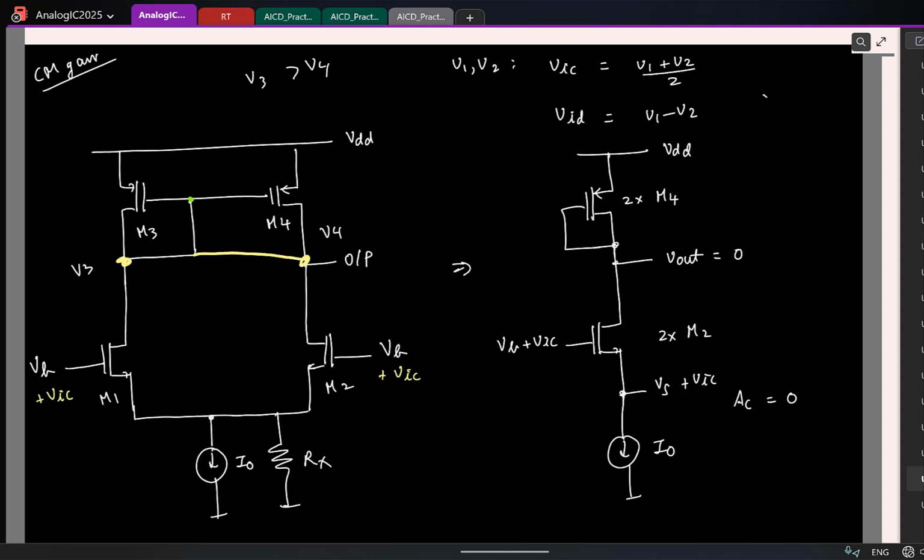Okay. In previous cases, for small signal calculation, we were just making AC ground to the current source. So for this calculation, why didn't we make these assumptions? Why did we never make this ground? There is a particular condition in which we made it. For the differential case. Yeah, but what are we considering now? We are applying what kind of excitation? Differential or common mode?